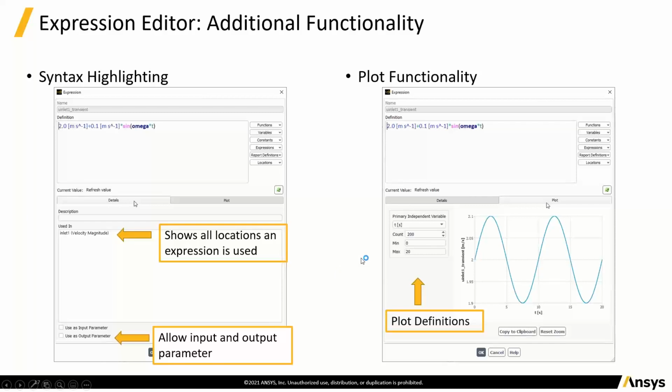Now, one of the benefits of this expression architecture going into Fluent is that if you go to any material that's got, for example, a specific heat set up, either through the standard NASA polynomials or through your own piecewise list or your own polynomial, they get plotted automatically for you.